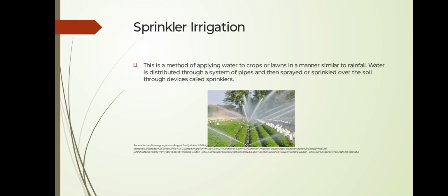Now, the sprinkler irrigation method. In this farm water application method, water is applied to the soil like a spray through a network of pipes and pumps. It is a kind of artificial rain and therefore gives very good results. It is a costly process and widely used in the USA, and it can be used for all types of soil and widely different topographies and slopes.